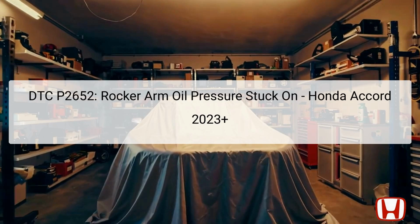The Diagnostic Trouble Code, DTC P2652, pertains to the rocker arm oil pressure being stuck on. This issue signifies that the output from the rocker arm oil pressure sensor is continuously high while the rocker arm oil control solenoid is turned off. If this condition is detected, the Powertrain Control Module, PCM, considers it an abnormal situation and records the code.